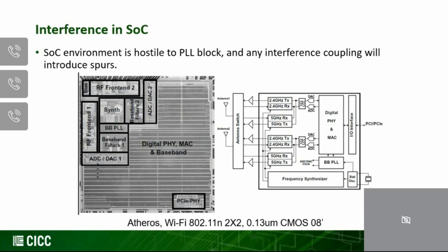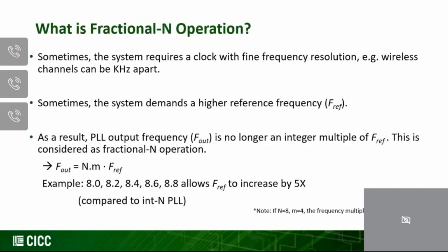external spur coupling. In terms of the internally generated spurs, I would like to focus on the Fractional-N spur generation. The reason is that the reference spur generation is a lot easier to mitigate, especially for digital PLL architectures, for the reason that I just mentioned, because the non-ideality in the analog circuit design no longer exists in digital PLL architectures.